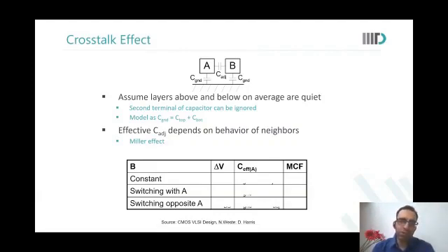Now you reduce 5 of them. Instead of 1 it became 2 ohms. But 2 is as low as 1. Compared to that, your driver's resistance is higher, right? Yes, sir. So you say, okay, let me have 2, or let me have fewer contacts than all 10 of them. That's not really a trade-off, in the sense that the resistance doesn't have that much impact in terms of magnitude. Because finally, if it is a very big driver, then the resistance of the global RC network is more important.